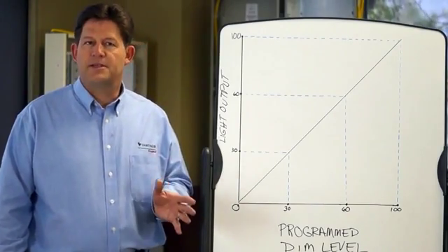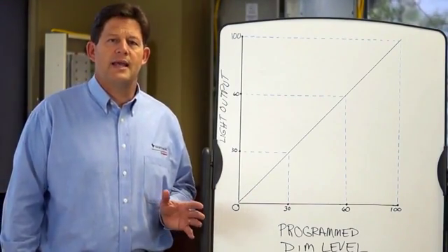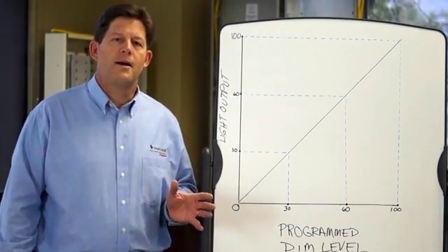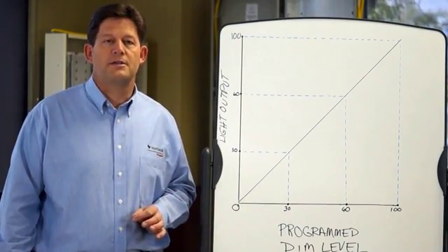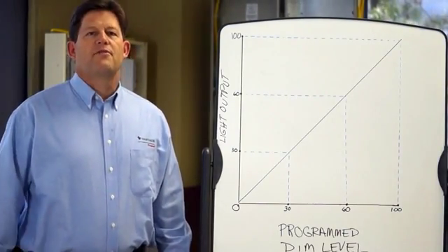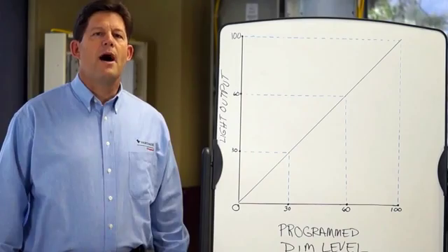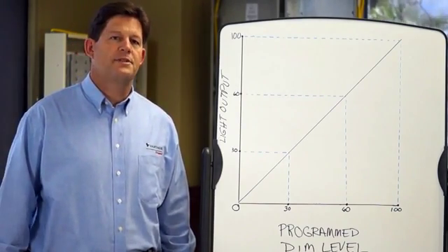Furthermore, once scenes have been set in a Vantage house, and then later incandescent lamps are replaced by LED lamps, unless linearity compensation is made for the new lights, all scenes would require recalibration. Vantage is the industry leader in compensating for nonlinearity. Let's examine nonlinear behaviors in LED dimming and what can be done with Vantage products to compensate.